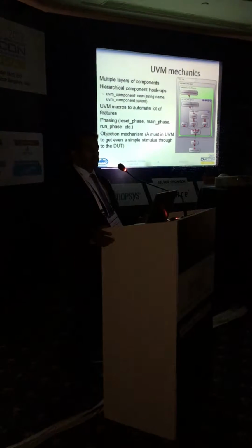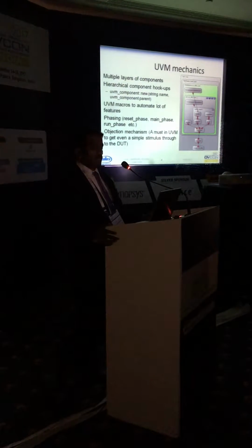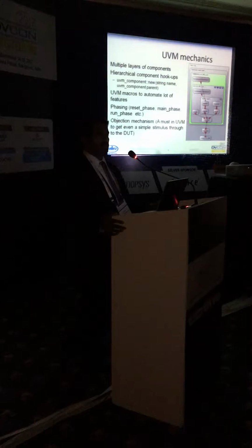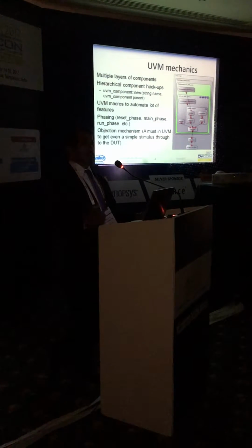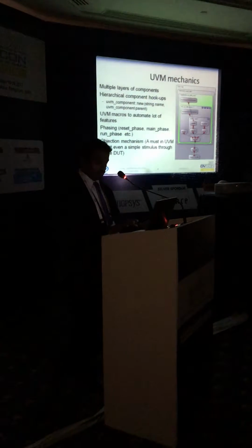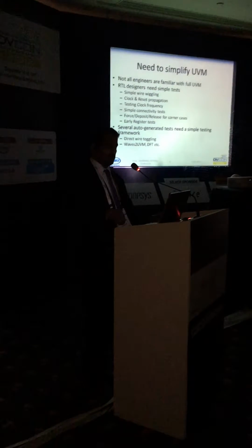Again, for those generated UVM benches, it's probably not a big deal. But trying to teach this to a non-UVM engineer is very difficult. You have to tell them you need to write this code called phase.raise_objection and then phase.drop_objection. So what can we do?